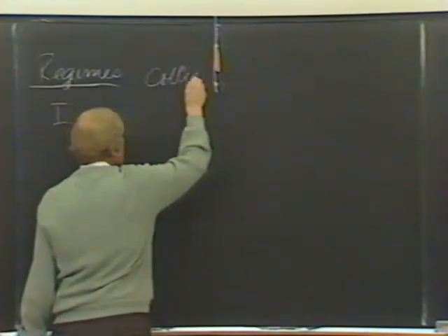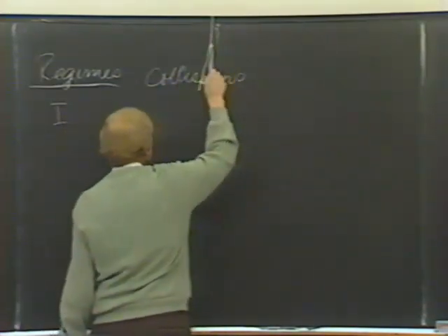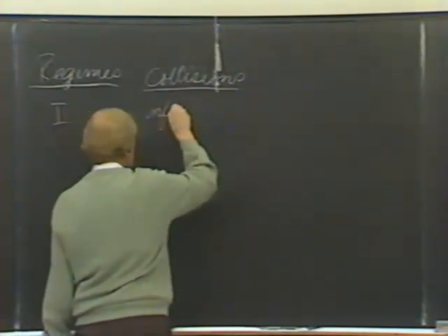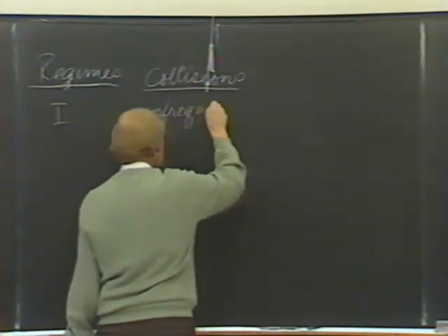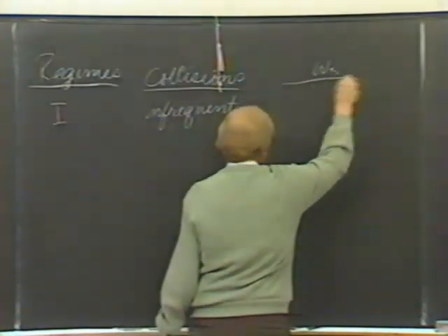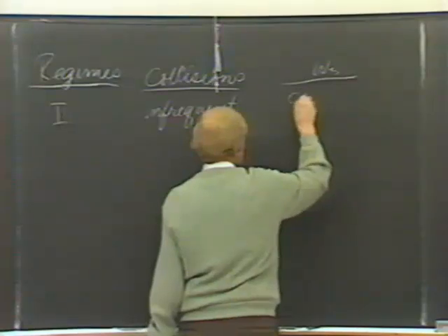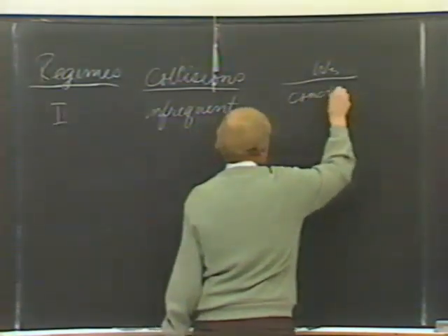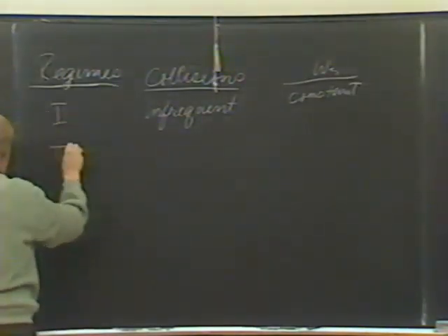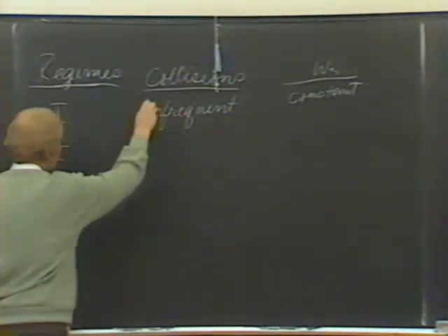The velocity gradient in the viscous layer is very high. It's the highest velocity gradient in the profile. So when the concentration is high, so there are a lot of aggregates to collide with each other, and the velocity gradient is high, then it continually breaks them up, and they mix upward into the waters above and re-aggregate and settle back down again.